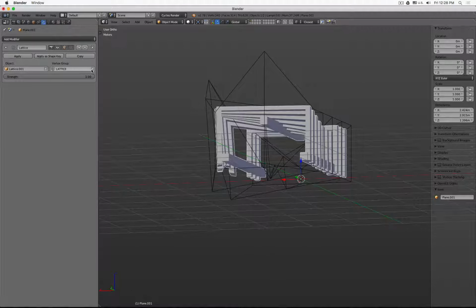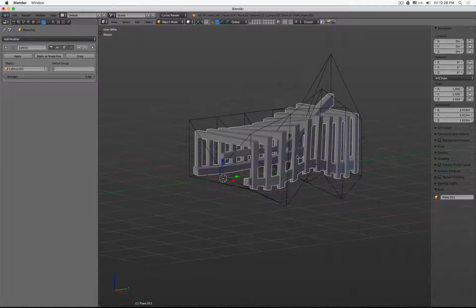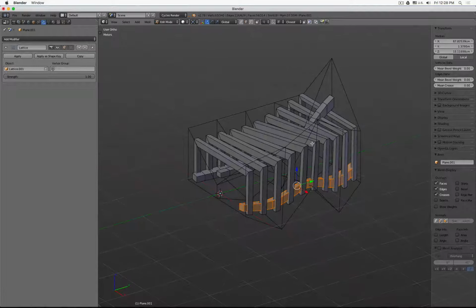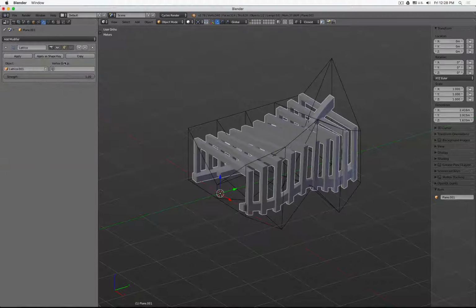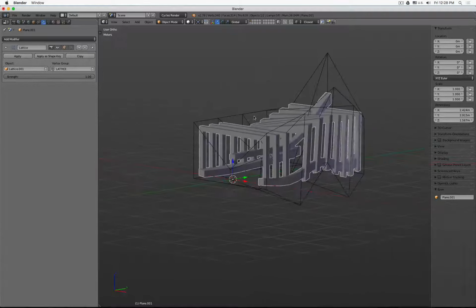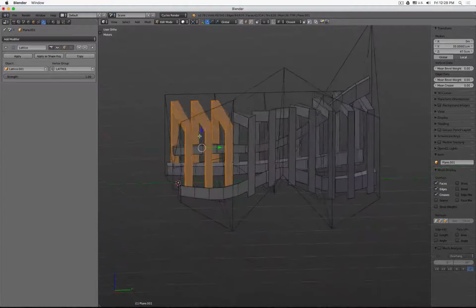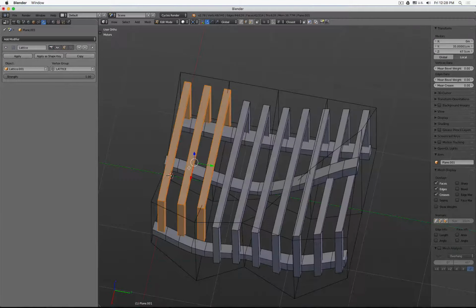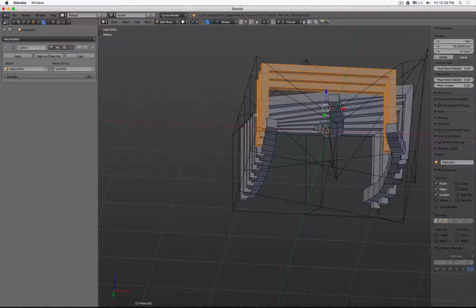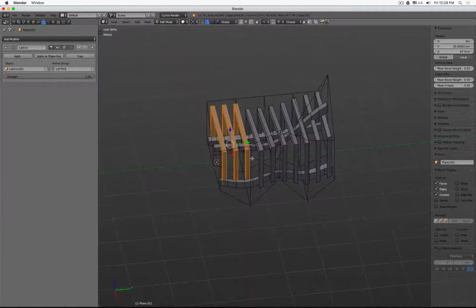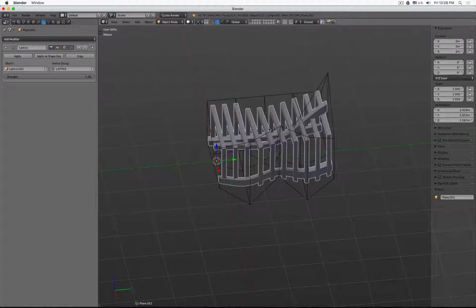But hey, what's going on with them? Well, they're not part of the deformation vertex group. So I would have to, for example, add them accordingly to the vertex group as well. Okay. And you see, of course, the first ones don't really work because they do not influence or are not influenced by the lattice. So if you want to exclude something, like in this case, I have to be a little bit smart and pre-plan the parts I want to be deformed and which I do not want to be deformed. But most times the lattice we can use to deform a complete object.